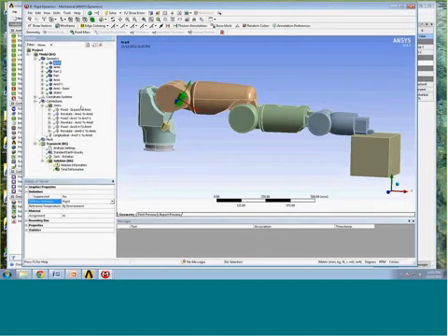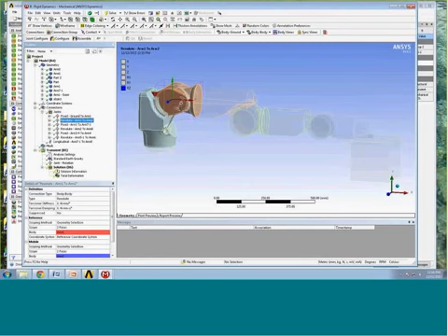In this case, we have a blue box next to RZ. That means the local coordinate system that's set up at the joint, and you'll see that right at the joint location, that RZ degree of freedom is free to move. So these two bodies that are connected to the joint are free to move in the Z rotational degree of freedom about that local coordinate system. Okay, so that acts as a hinge. And we can apply loads directly to that joint.